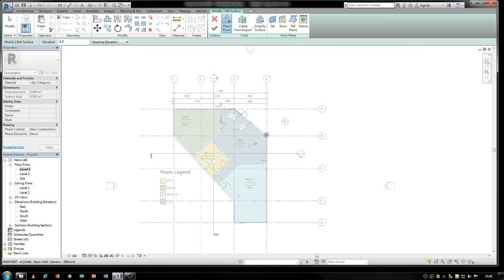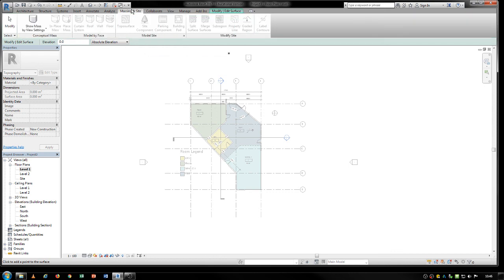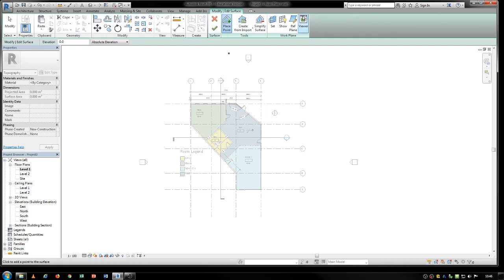Alright, so if you don't have a CAD file, then you would build your topography here. The way to do that is by placing points. So when you click on Place Points, again under Topo Surface, it will give me these tools to work with. You place the point, and it has the elevation defined for those points. So I'm starting at 0, placing a few points around. That's one round. Then I would go maybe a few meters higher,